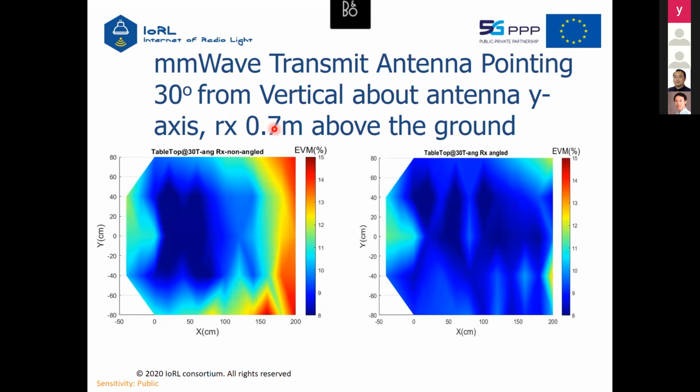In this case, we put the receiver on the table. So the table will shield a lot of reflection, and the multipath will be slightly better. In this case, the channel estimation window will be handled. We can handle the equalizer well enough for the local reflection from the ground signal.